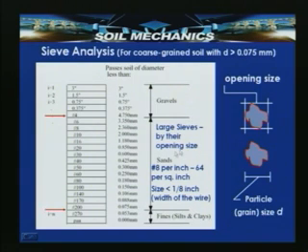So, larger sieves are indicated by the opening sizes. For example, here number 8 sieve indicates that the number of holes per inch is 8, that means that 64 holes will be there in a square inch. So, the size of the hole or the size of the mesh will be less than 1/8 of an inch, because the width of the wire comes into the picture.